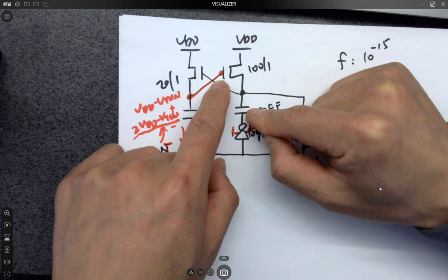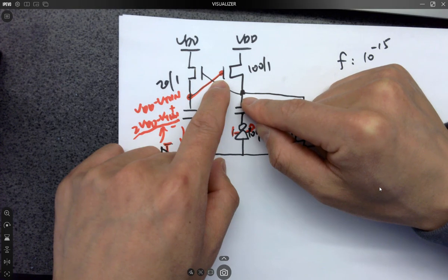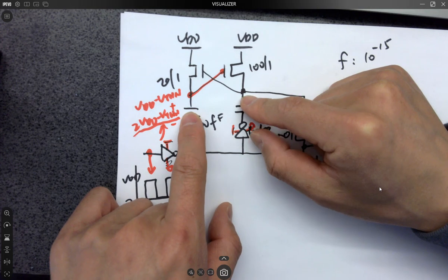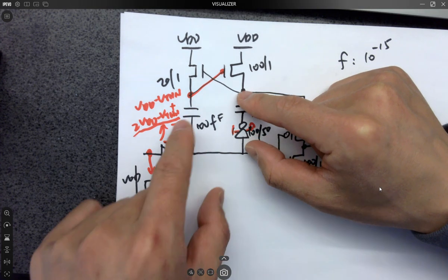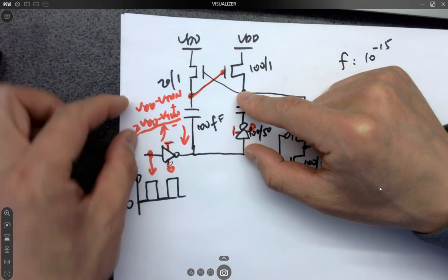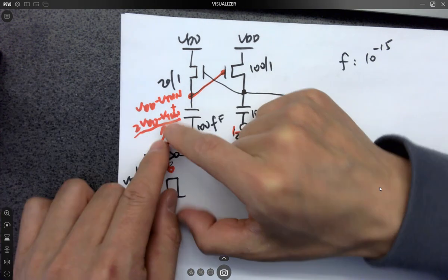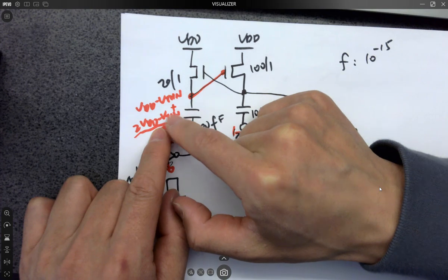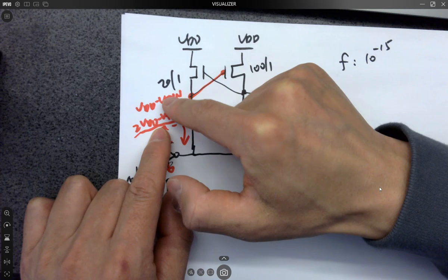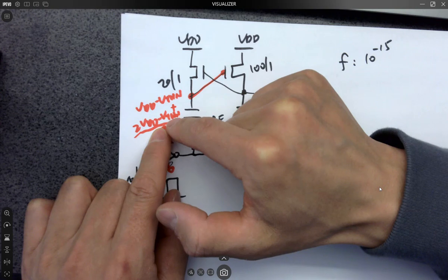One of the most important points we have been trying to cover in the recent 2 weeks. Okay, so whenever this is pushing, it's adding 1 VDD to this value, so we are getting a higher voltage, the higher one of the 2 voltages available, right? So it's oscillating between these 2 voltages and becomes a higher one. And this higher one is larger than VDD, we can tell, and this one is smaller than VDD because the minus is subtracting the VTHN from the VDD, okay? But this one is definitely larger than VDD, okay?